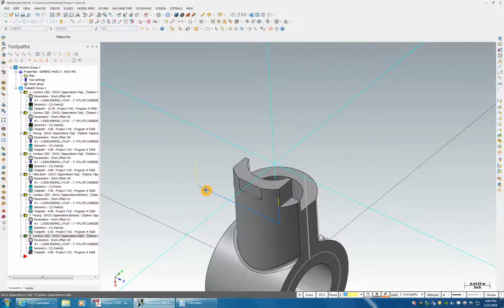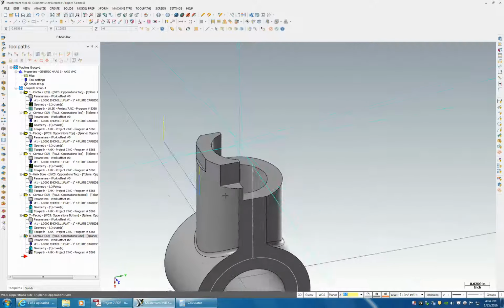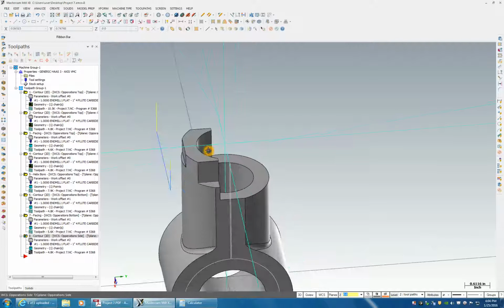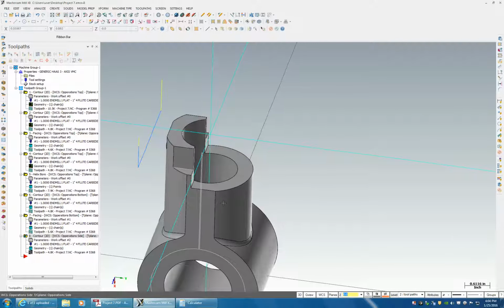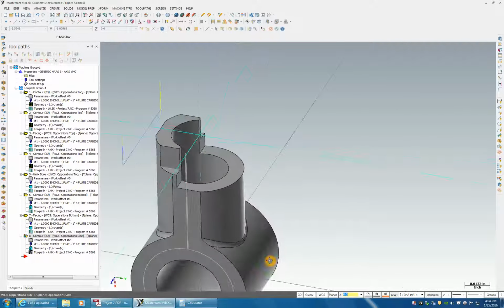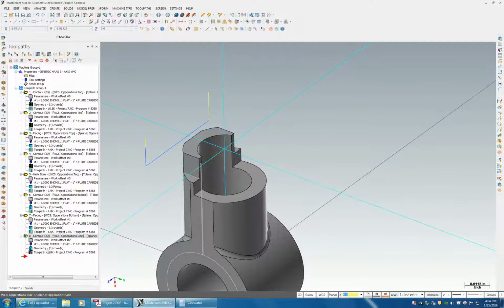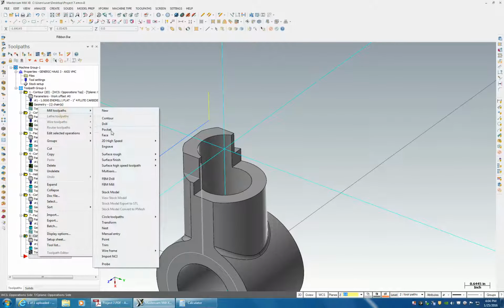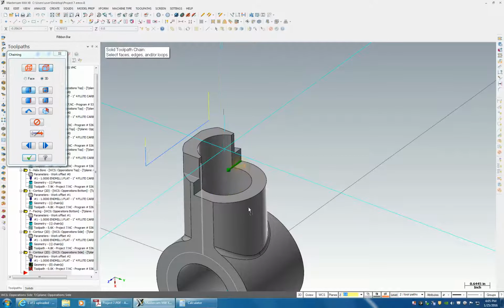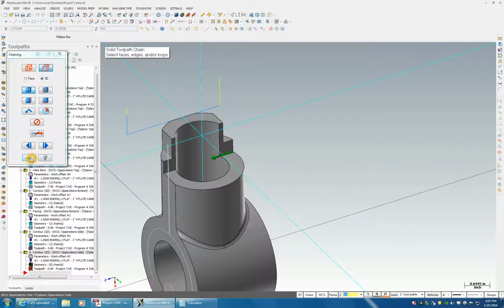Okay. So that will come in and cut that off. We also need to cut the top of this off, but I'm going to cut this out first. So, mill toolpath, and there's some changes we're going to have to make to our toolpath here because the way it's currently run is not working. But let's contour using that line. It's going the right direction.